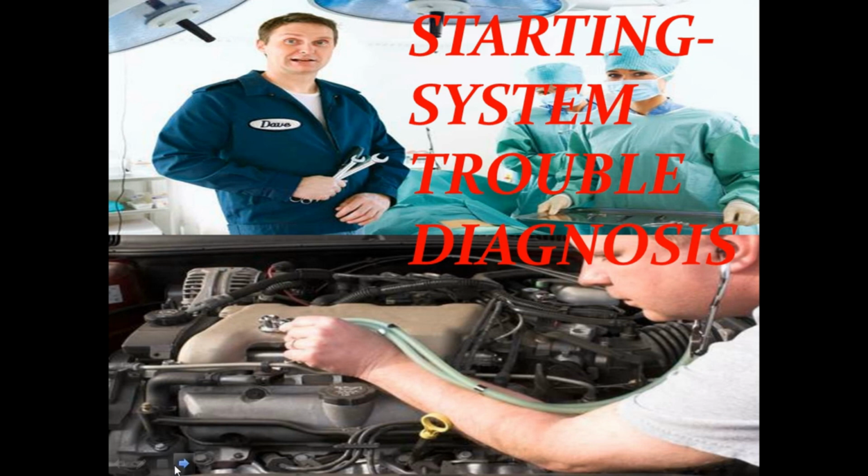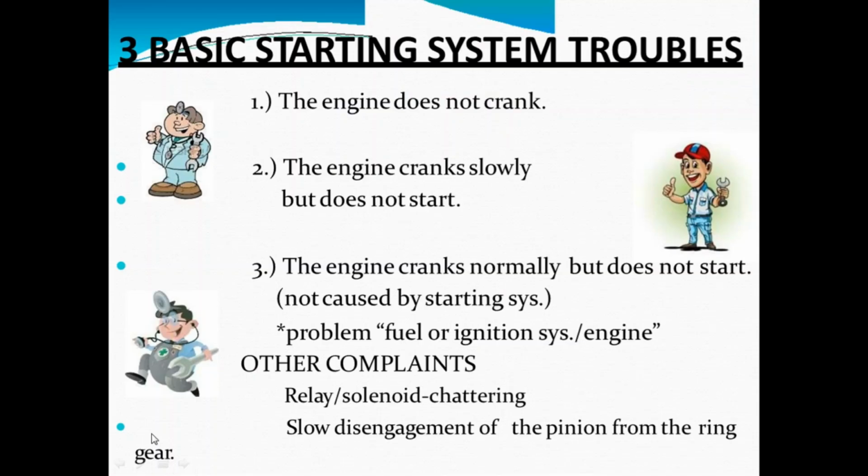See, there will be some troubles. Basically, when the vehicle breaks down, first we check the battery, whether the electrical supply is enough to start the engine. So, a basic starting system trouble is that the engine does not crank. When we ignite the ignition switch, the crank does not rotate. So there is a trouble in the starting system, and we have to check all this.